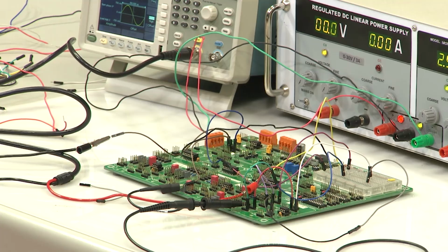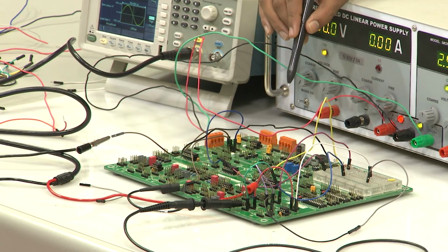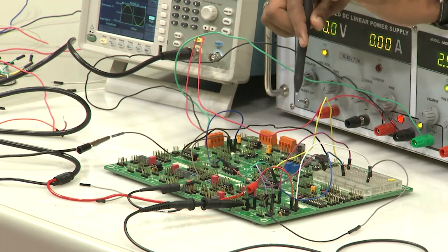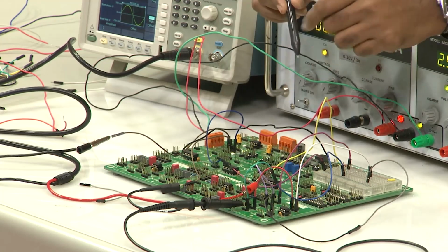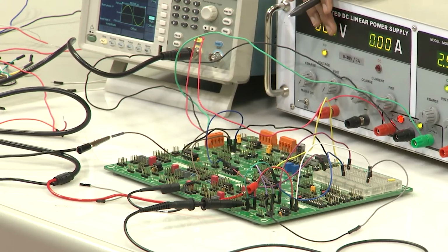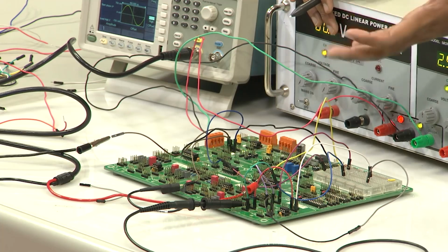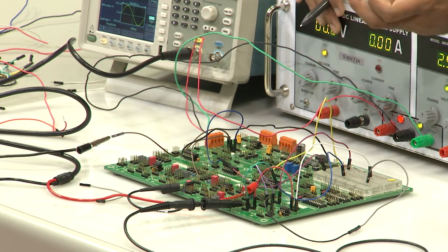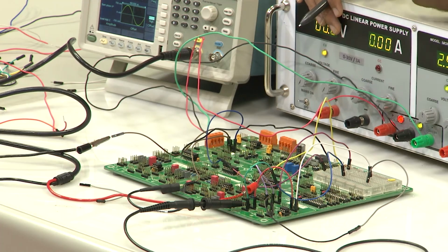Just a quick recap, what do we mean by the range? As we know, the op amp has a saturation voltage which is around 13 volt, 13.5 volt, when the supply voltage is around 15 volt. Because the op amp has a gain, when we give an input, we get the output multiplied by the gain, which here is the closed loop gain. So, what is the range of the op amp? The range of the op amp is the range of input voltages that give corresponding output voltages without saturation. That is, in practical terms, the range of an op amp based amplifier circuit.